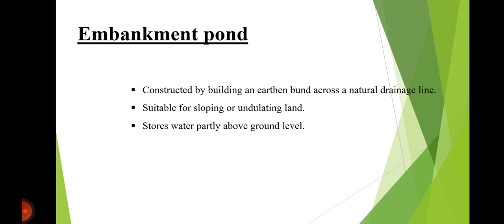The second point is less excavation work, and it is suitable for regions with considerable runoff. Some of the disadvantages are the possibility of embankment failure, required spillway construction, higher maintenance and safety considerations.